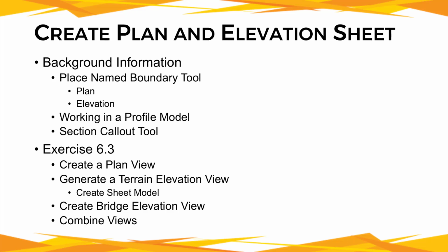Next, we'll start going through exercise 6.3 step by step and create the plan view that will be included in our plan and elevation sheet. Then we will use the profile model to generate the terrain elevation view and also create a sheet model through that. Next, we'll create a bridge elevation view. And then finally, we'll combine all views into one cohesive plan and elevation sheet.